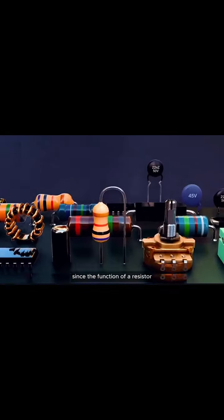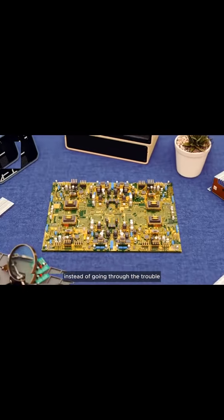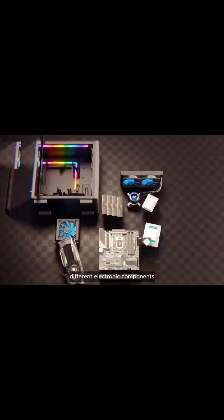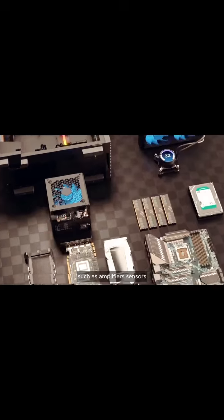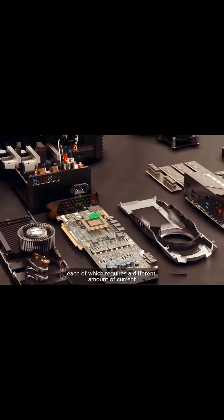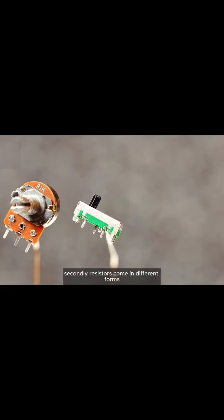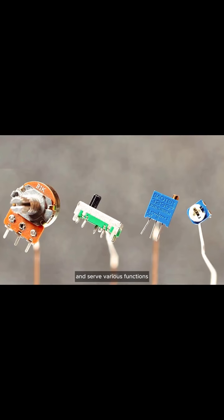Since the function of a resistor is to regulate the amount of current, why not just set the current to the desired value at the input instead of going through the trouble of using a resistor? First of all, a complex circuit contains different electronic components, such as amplifiers, sensors, and various chips, each of which requires a different amount of current. Resistors can allocate different currents to them. Secondly, resistors come in different forms and serve various functions.